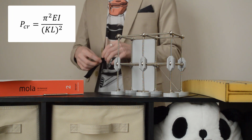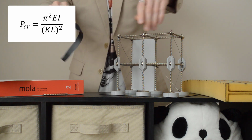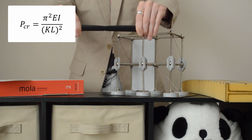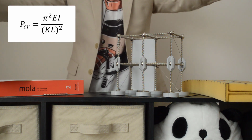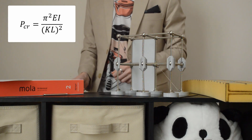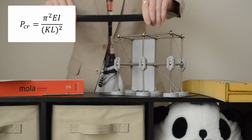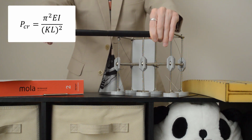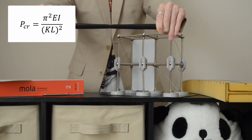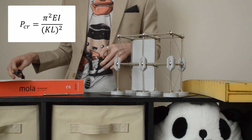We're going to do that by pulling on this piece of electrical tape. You can see as I pull on this, it starts to yield, and then eventually, if I continue pulling, it ruptures into two separate pieces. And just in case you missed that, I'm going to do it again, this time with a bit longer piece of tape. And again, as I pull on it, note that there isn't really anything much going on here aside from it elongating in the direction that I'm pulling on it. It starts to yield, and then it ruptures.